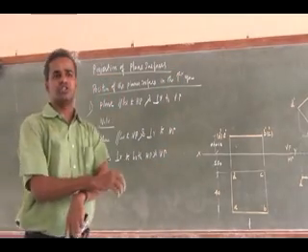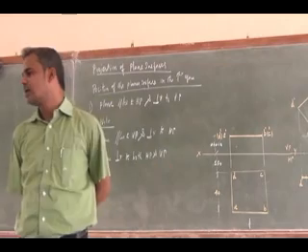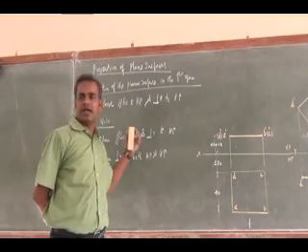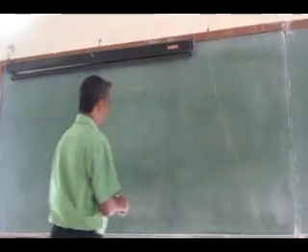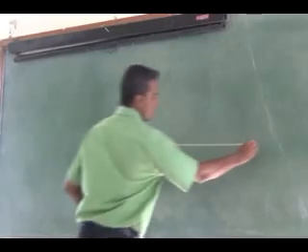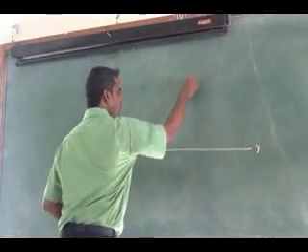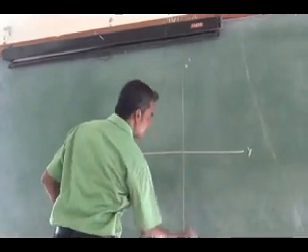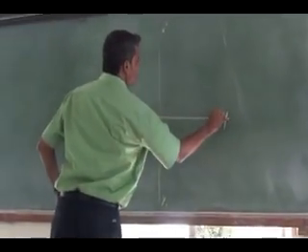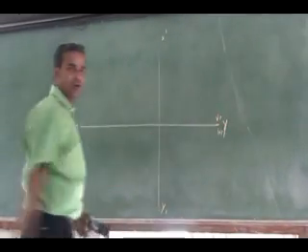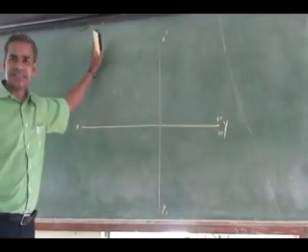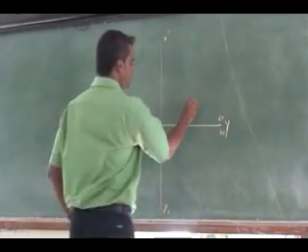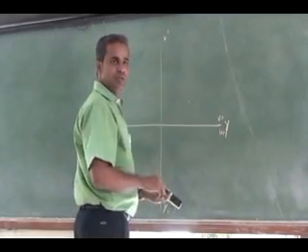To draw the projections of the plate, if the plate is perpendicular to both HP and VP, now I can draw it. Draw the reference line X, Y. So I am going to draw the VP, HP. Right. So I am going to draw the side view. Side view will be on the right side. So the right side view will hold the true shape of that plate.